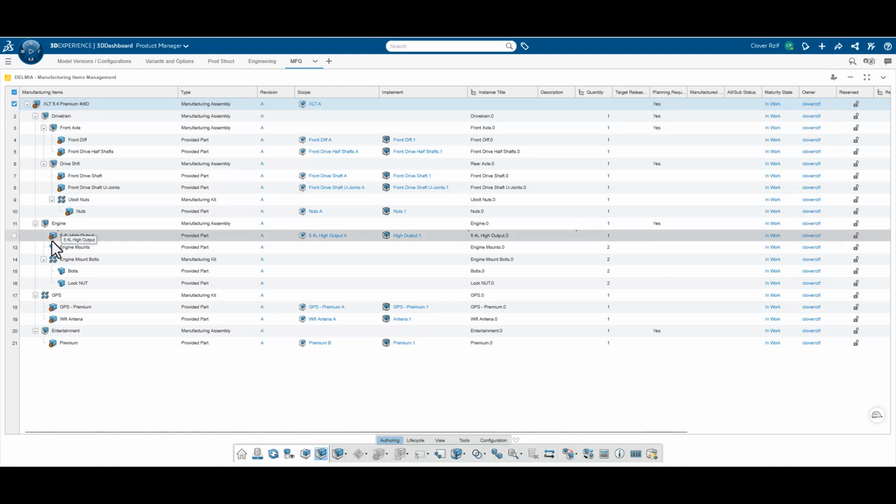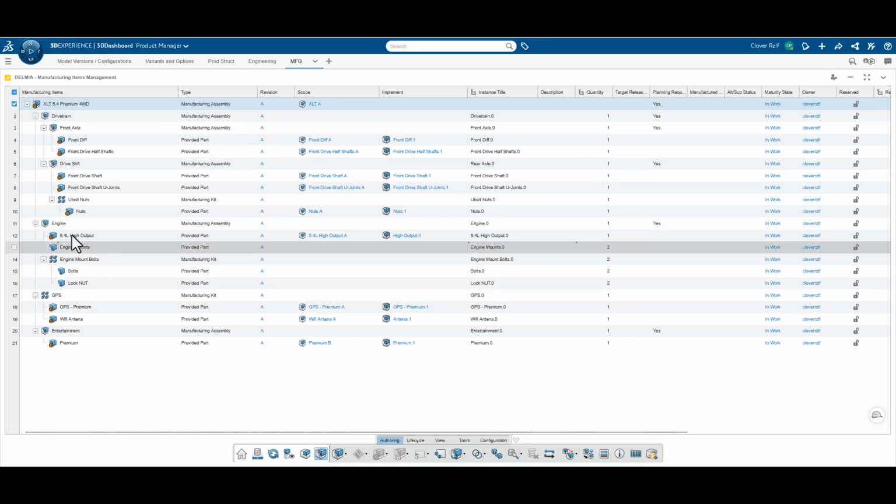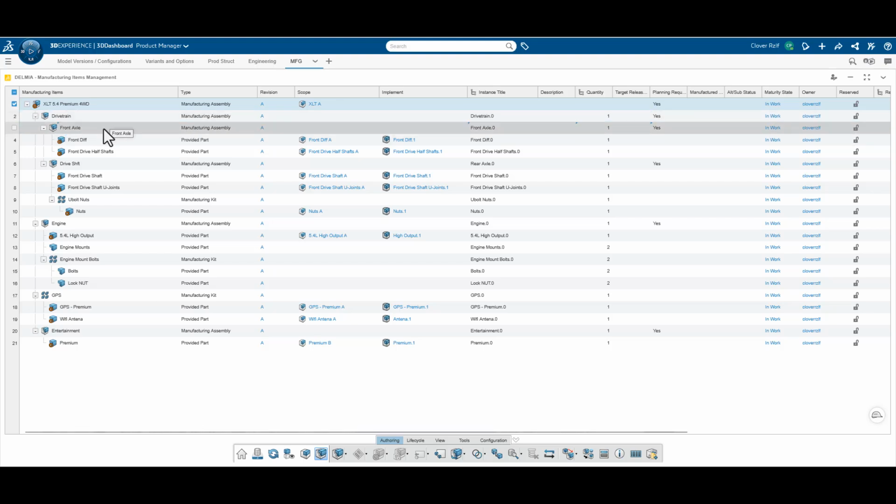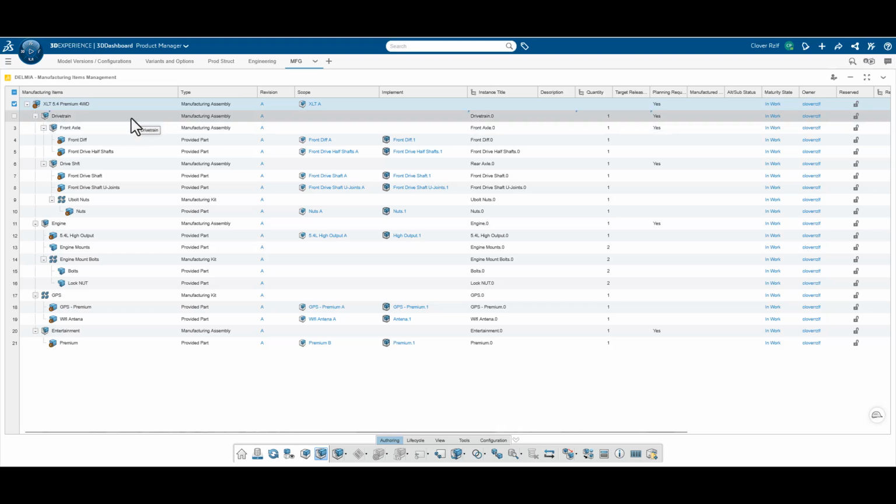Now I've added in the other components, the other categories or different areas, and these may be components or structures for manufacturing on how they need to assemble, build, or machine or process that component. So I might have a drivetrain and break these things down from engineering in a different order than what engineering has it, because I might have to put several components together, ship it over, be welded, primed, and other processes done. So I may need to group these in a different way than what engineering had them. So we can create manufacturing assemblies.